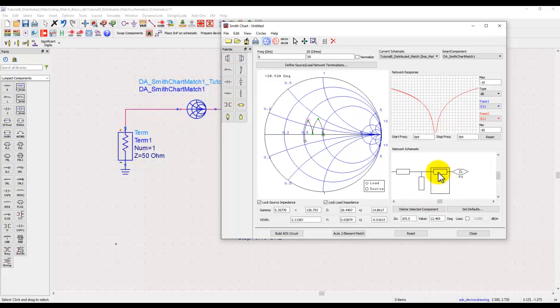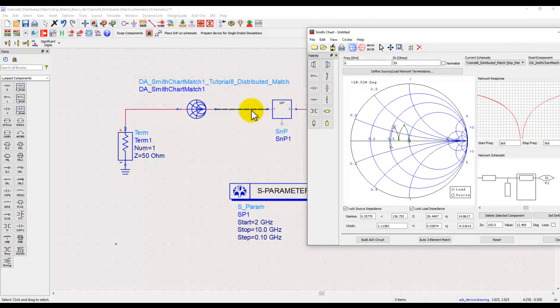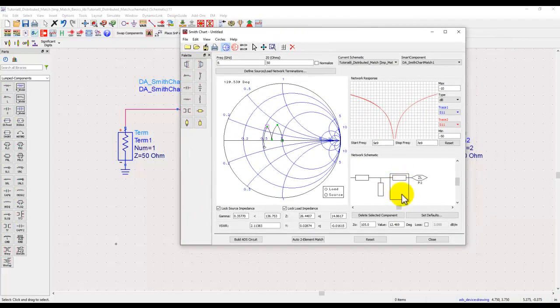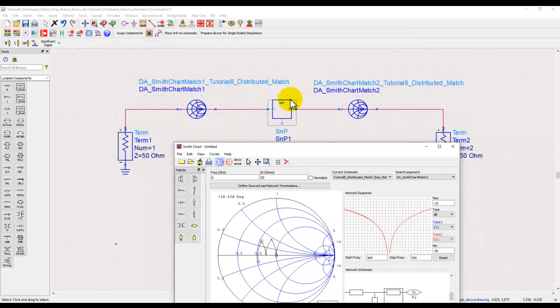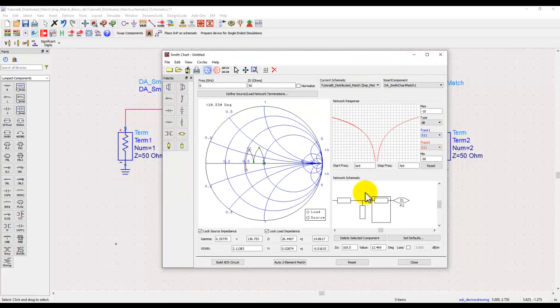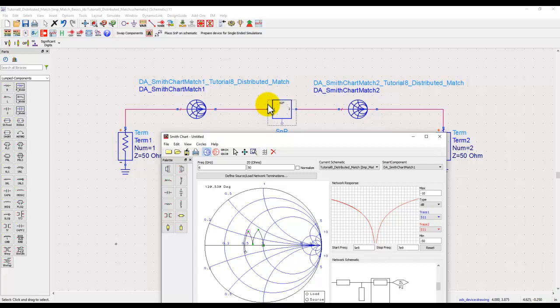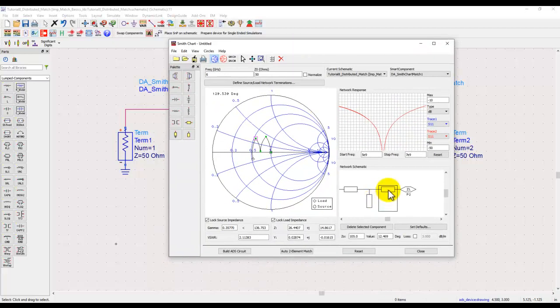And then on this side, because this SMT component lead will land, I need to make sure if I want to utilize this line for my component lead placement. If I'm going to have another footprint for this S2P which I want to associate, and it already has a lead to mount, then I don't need to worry on this side because the footprint will start from this location. But sometimes people want the footprint to land directly on this line so that they can even reduce the size. So if you want the footprint to be landing on this line, then this impedance has to be set as per the width of the pin which you are going to have. For now, I'm going to assume this is fine.